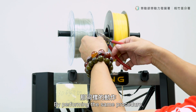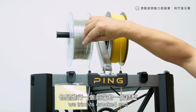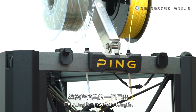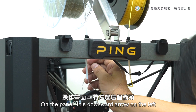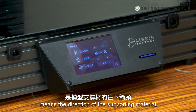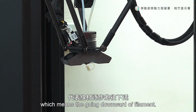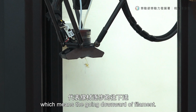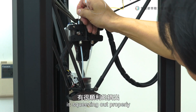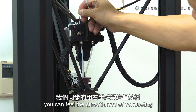By performing the same procedure, we put in the support material. Like the previous one, we trim the hooked end and feed it through the other white tube, feeding in a certain length. On the panel, this downward arrow on the left means the direction of the supporting material. You can also see the extra filament is disappearing, which means it's going down. Then check the nozzle to see if the end is squeezing out properly. Again, use your right hand to feel the smoothness of conducting.